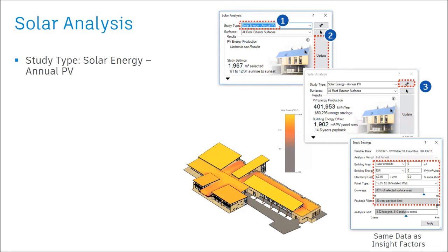And essentially, you'll see they're mirrored in Insight, so that when you're looking at total building energy and the contribution of PV to the total building energy, you can actually coordinate between the two of these, meaning the solar analysis can do the detailed study, surface by surface, or even down to detailed panel by panel design, and Insight can track that as part of the overall total building energy contribution.